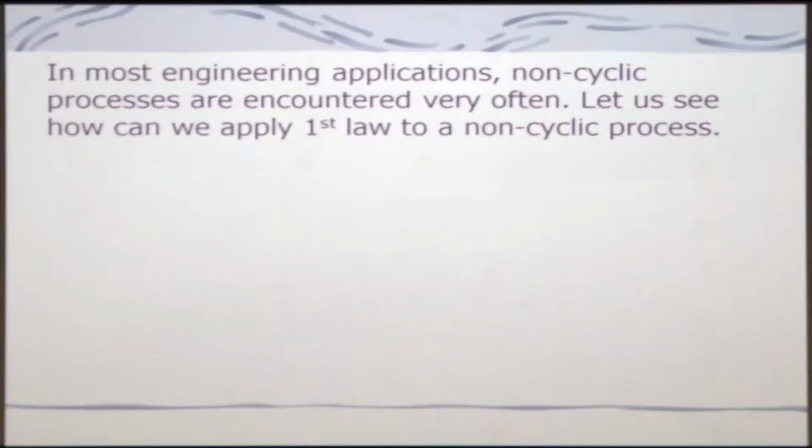For example, let us say there is a gas cylinder, and it is being leaked out, right. Can I get it back to the original? It needs work to be put into that, so it is not cyclic. However, there are several cyclic processes also, as I told, like your automobile engines. It is cyclic, it goes on working and giving heat and other things. So now we need to see how the first law of thermodynamics, which we have discussed just now for the cyclic process, can be extended for a non-cyclic process.